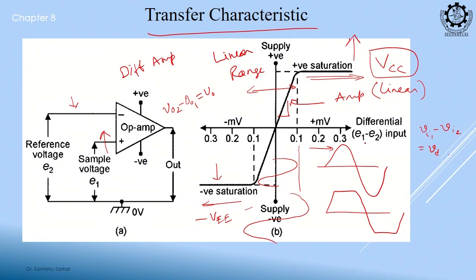But in this plot, the x axis is some DC voltage. So, this is known as the DC plot. The previous one was a transient plot. Why transient? Because the x axis variable was time. Here the x axis variable is DC voltage. So, this is a DC plot, that was a time plot. If the x axis is frequency, it will be an AC plot or frequency plot.